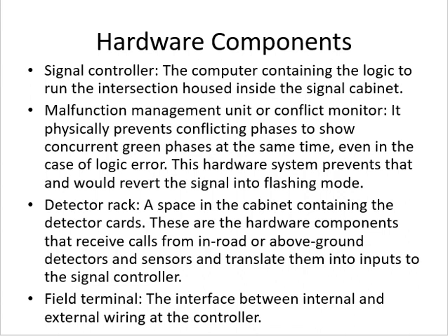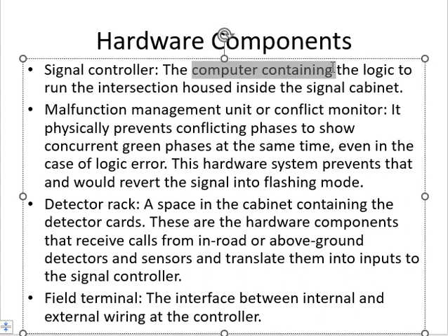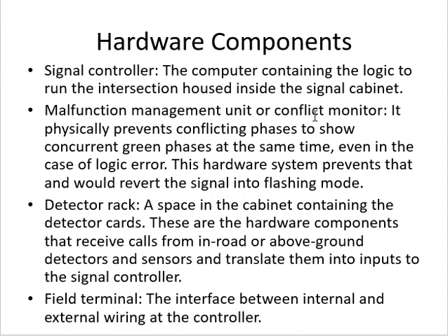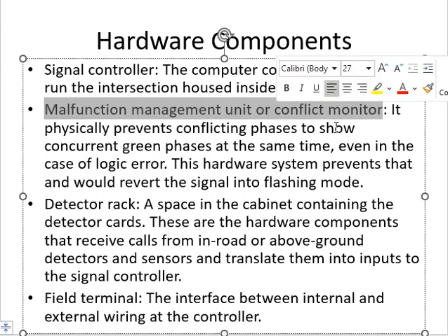Then we have the malfunction management unit, or the conflict monitor. This conflict monitor is basically applying some rules on the logic which you have provided to the computer. This logic is checked under some rules, and whenever there is a rule violation, the malfunction unit or the conflict monitor will detect it.